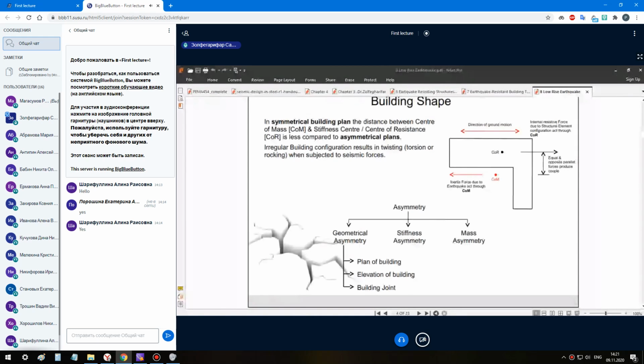Asymmetrical plans undergo a large amount of torsion, and hence extreme corners are subjected to heavy forces. We should avoid asymmetrical buildings like L, U, and T-shaped buildings. In buildings, we should use symmetrical shapes for more strength.